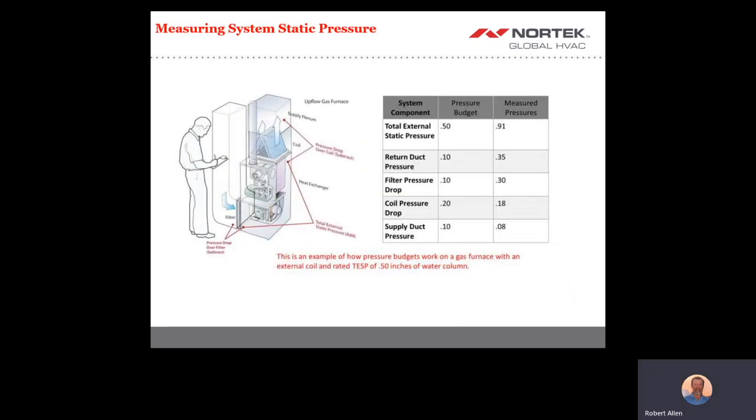Diagnosing static pressure is straightforward. High static pressure and evidence of low airflow may indicate restrictions in the airstream. I would check for blockages in the ductwork, closed dampers, improper transitions, offsets, or kinked flex duct. The same is often true of low external static pressure and suggests a low fan speed, leaky duct system, or possible missing filters. Both deserve, of course, further diagnosis to determine those airstream issues.